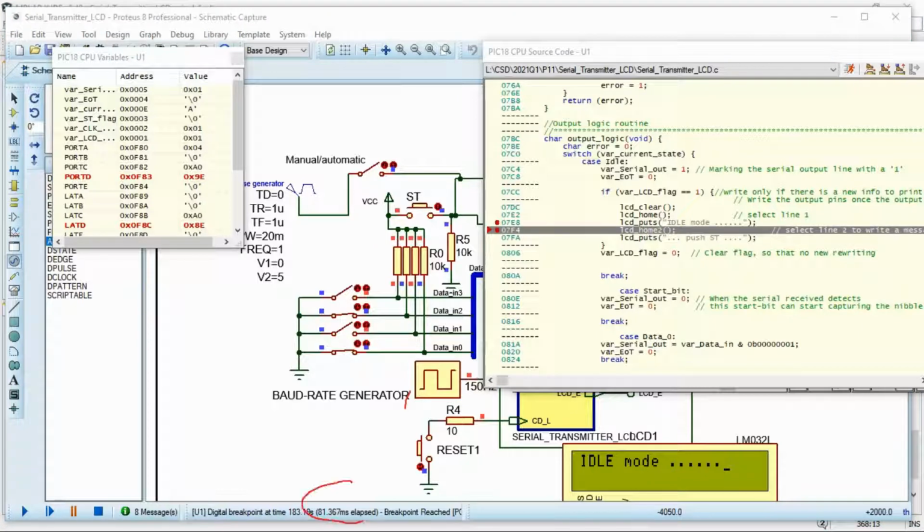Look at this. This is the measurement that I like to perform. You see, it has taken 81.36 milliseconds. Remember, this is 7 microseconds. So you see, 7 microseconds, but it has taken 81.3 milliseconds, all that time, 81,367 microseconds to execute this single instruction here. And this is something that you have to consider carefully in your applications, right?